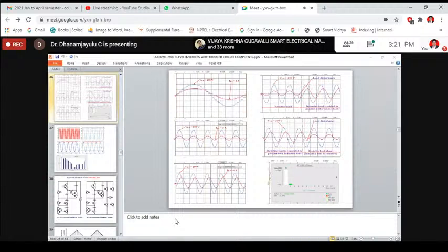My suggestion is that you can take a SEPIC converter. In the SEPIC converter, the secondary side has an inductor. By employing the inductor, you can get single input and multiple output voltage levels by having mutual inductance.